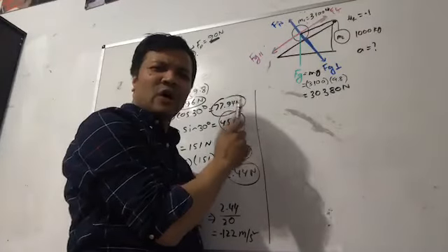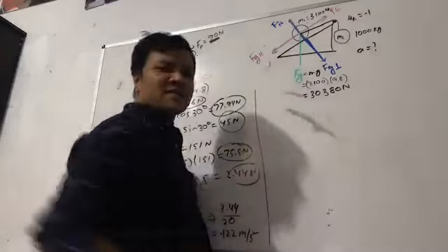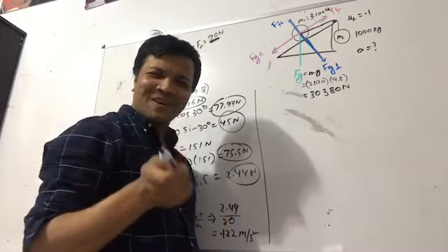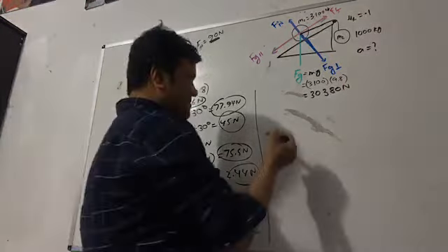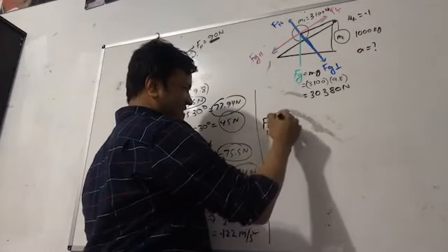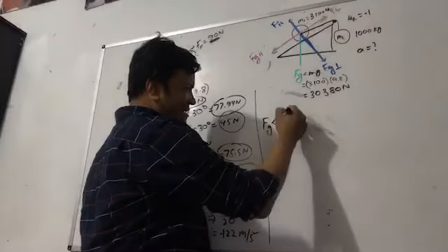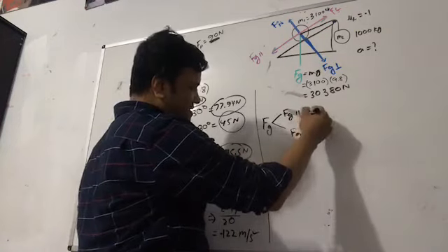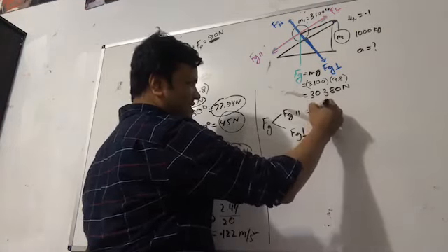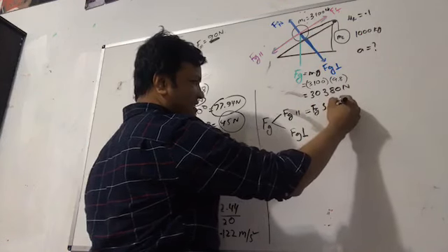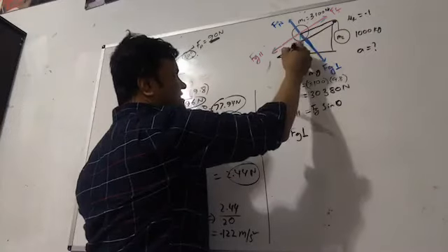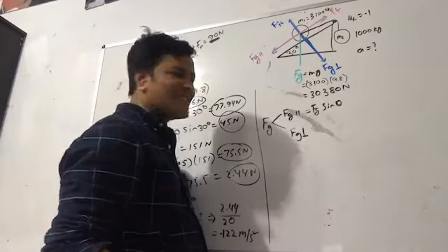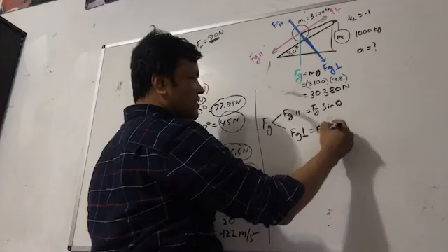This is the weight of this box. Now the gravity has two components because it is sitting on an inclined plane. So now let's find both components. Fg has two components, Fg parallel and Fg perpendicular. Fg parallel is by definition Fg sine theta. And let's say the angle is 30 degrees. It is a 30 degree incline. All right. And Fg perpendicular is Fg cosine theta.